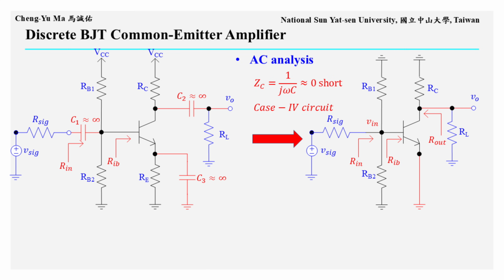They block the AC signal from disturbing the DC bias. For AC small signal analysis, the impedance of a coupling capacitor, 1 over j omega C, approaches 0 if the capacitance is large enough. Therefore, in discrete amplifier design, coupling capacitors are usually chosen large so that they behave like short circuits for small signals and do not significantly attenuate the voltage signal. Also, DC voltage sources become short circuits to small signal ground.